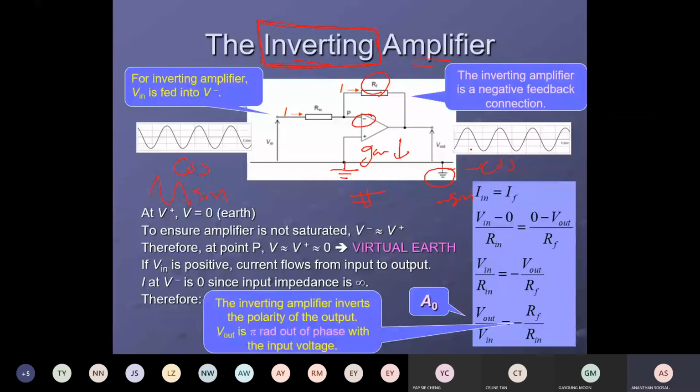Let's say the power supply is positive 10 volt, the input signal is 2 volt, and you put the gain as 4 times. The maximum you're going to reach is 8 volt, so still within the power supply range, you retain the pattern. If the gain is 10 to the power of 5, this is definitely going to be a square wave because you're going to saturate to 10 volt. So that's why feedback.